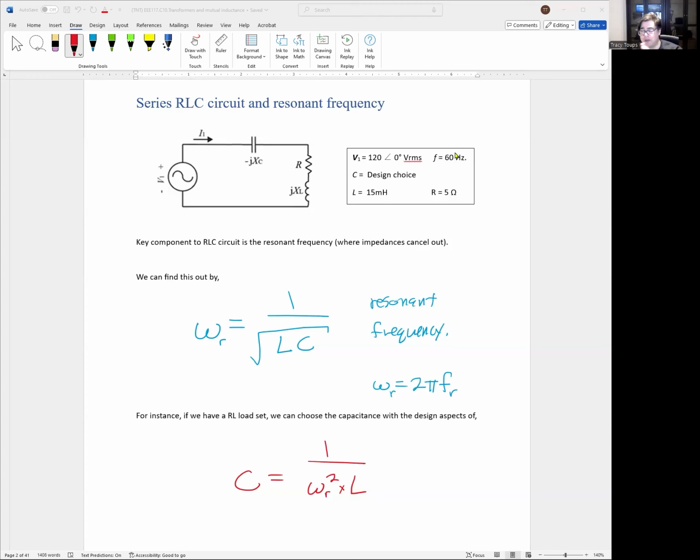But the further away we get from this resonant frequency, the inductor or capacitor impedance gets bigger and bigger and bigger, right? So think about the resonant frequency as a perfect point where you have the lowest impedance, and anywhere past that, going to a greater or lesser frequency, the impedance rises. It's kind of like a V shape where the bottom of the V is the perfect resonant point, and the impedance grows higher and higher in both directions, going to higher and lower frequency.